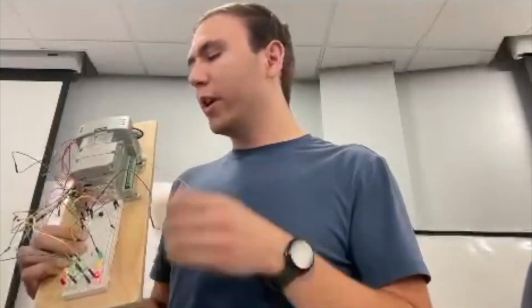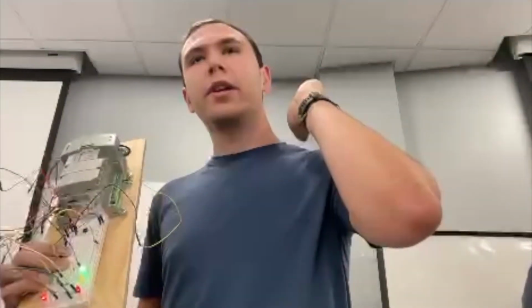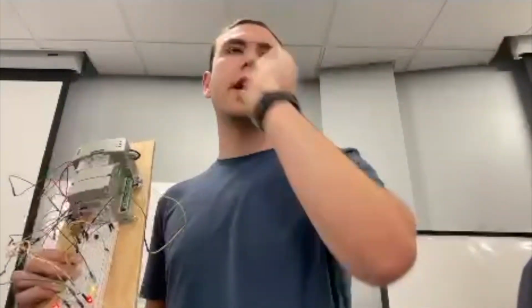So it's slowly going through this scan cycle where it's reading the inputs. There are no inputs. Then it's running through its program logic where it's deciding, hey, what state am I in? Am I saying everybody's green this way, but everybody's red here, or is it the yellow and red, or whatever that is? And you just continue cycling through that. So yeah, that's that. If you have any questions or want to see the actual code for it, come up after the meeting and I can show it to you. It's on another computer, so it'd be really hard to get up there. But that's essentially what a PLC can do.